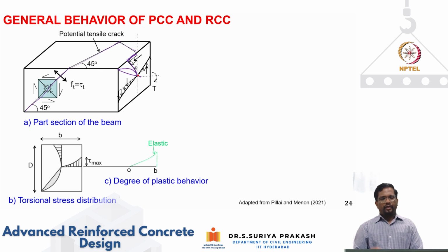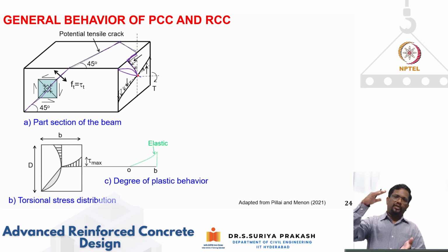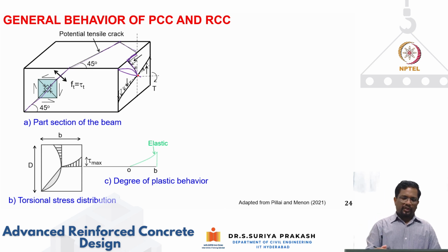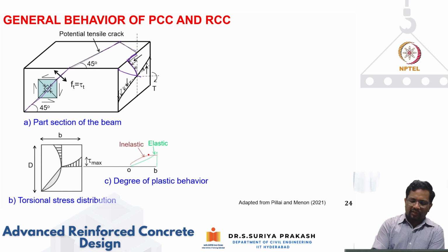And in reinforced concrete we put a lot of steel. Concrete in general, as a material, if you look at it, whether you test in compression or tension, up to a certain point it is actually elastic, and then it becomes nonlinear and inelastic. So you can model the shear stress distribution as an elastic stress distribution, or, because we are putting a lot of reinforcement, we recognize that the material is actually not elastic, it is inelastic. You can model the shear stress distribution as inelastic also.